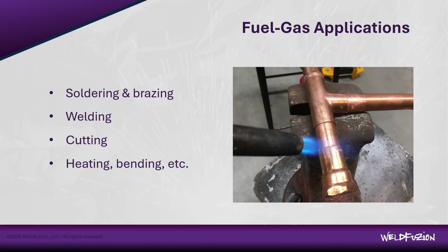However, it's super slow, has high heat input, which can lead to severe distortion, and has limited thickness capabilities in terms of welding. It also doesn't provide the best shielding, which actually comes from the chemical reaction that releases carbon dioxide during the combustion of the gases. So it can't be used for high purity materials or highly alloyed materials like stainless steels. It's just not suitable.